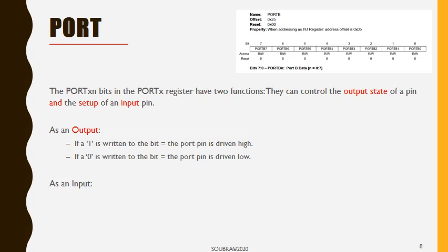Alright, here we have two different scenarios. The first one is the one that I started talking about, where I decided that my port B, let's say, is all configured as output. So in the DDRB, I have ones everywhere. So everything is an output.